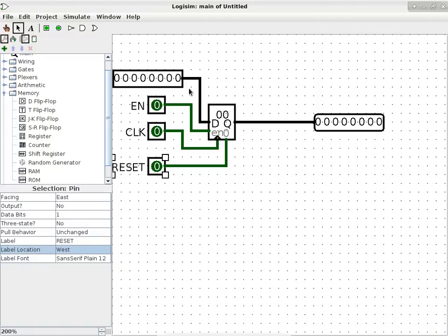So I want to change the state of the register to something. Let's say we want to change it to C7 in hexadecimal, because this is in hexadecimal. To change it to C7, I need a 1100 here for C, and the 7 is 0111. We'll talk about how to do the base conversion in some other class, but this is the state I wanted to reflect over here. I want a C7 here. It's not doing a single thing because, one, it is edge sensitive to the clock, and two, the enable pin is a 0.